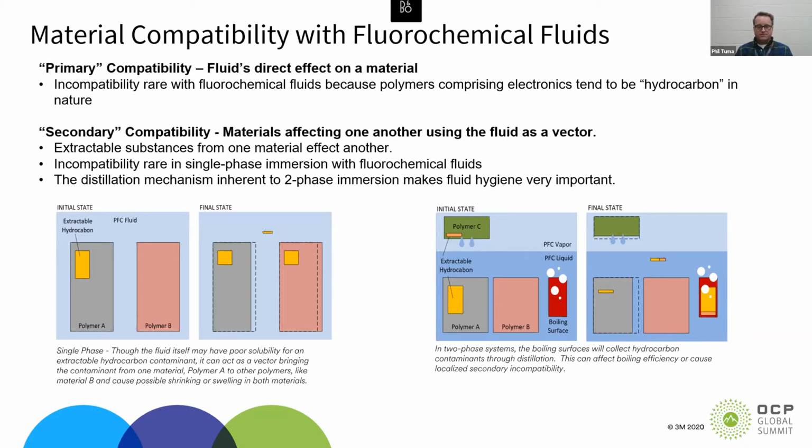You also have boiling surfaces, of course: the processor, FETs, voltage regulators, diodes. These things are all boiling, and a modern processor can distill hundreds of liters of fluid per day. So the contaminants that become solubilized by the fluid can deposit there, and this can affect not only thermal performance, but in extreme cases, it can affect the reliability of the device. Next slide, please.